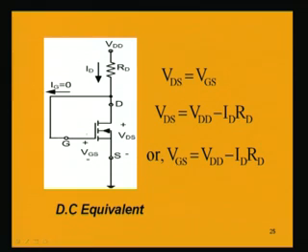So, if we now draw the DC equivalent circuit, forgetting about the AC input, we are having this circuit which is having the resistance Rd at the drain and gate being short circuited. This circuit is bereft of the capacitors, since this is the DC equivalent circuit, the capacitor is making it open circuit for DC.